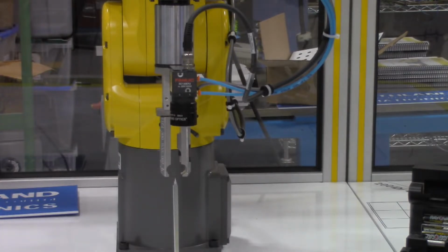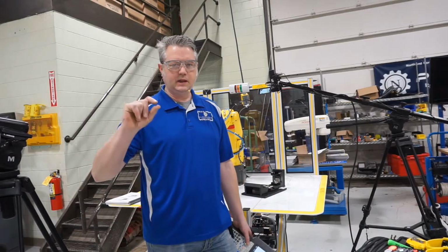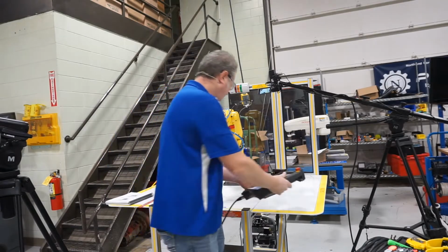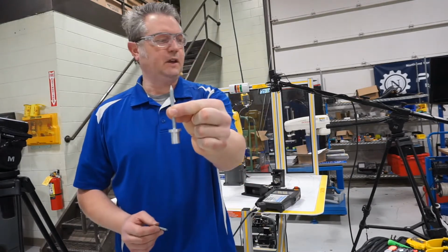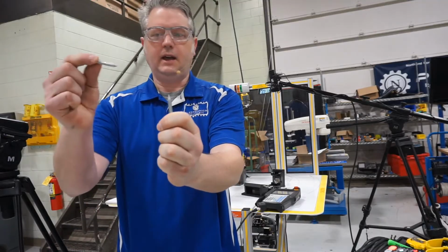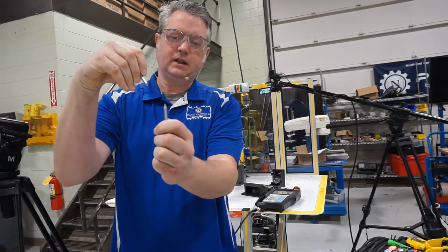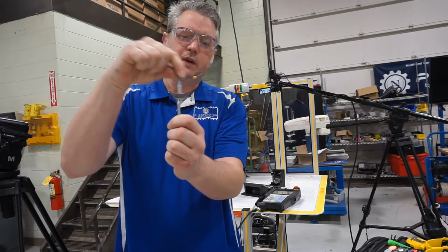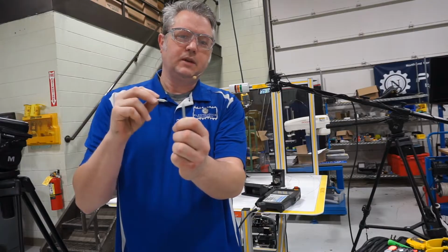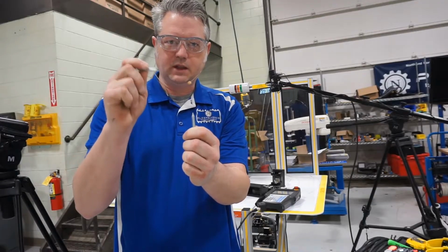EOAT is the acronym that's used for this. So let's talk a little bit more about these details. So in tool frames you have the ability to program in an offset, and basically you've got, say this is your fixed point that you want to get to. And here's the robot arm, and as you're jogging it around, it would be sort of a pain if we had to compensate for this and say we had a really long tool and we want to get to a certain point in space and jog it around. It's a lot more user-friendly if we can tell through the software where the tool center point is.